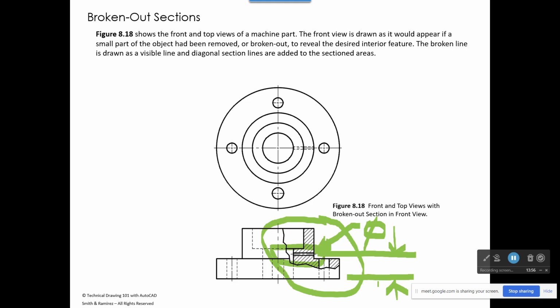So if you look in the ASME standard, you'll see all these examples here. Okay, so look at this irregularly shaped line that we have right here. When you draw that line, probably what I would do in AutoCAD is use the command called Polyline. And it's on your draw toolbar.